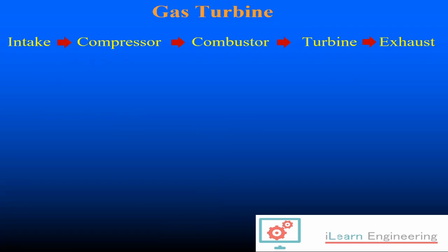If we look at a basic configuration for a gas turbine, initially we have an intake, which will take the gas in and compress it some way, in other words, increase the pressure. Then send it through a combustion chamber, in other words, introduce some further energy to increase the pressure and the temperature even further, so the kinetic energy of the gas is being increased. And then you pass it through a turbine, which is connected to the compressor to turn that, and then through some nozzle and exhaust system to help you produce some net thrust.